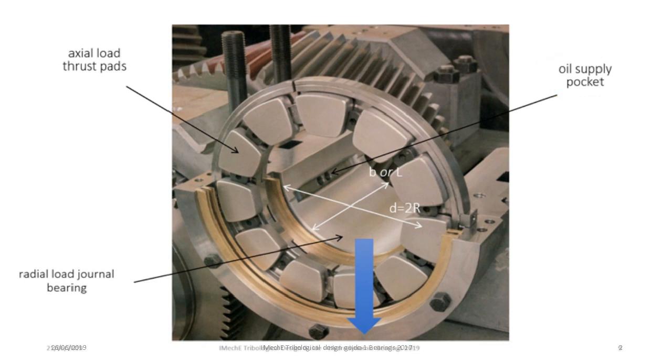Oil must be supplied at sufficient rate to compensate for its loss from the ends of the bearing. The ring of 11 more or less square pads are designed to carry the axial load. They are tilting pad thrust bearings. We won't talk about their design in this session, but they too depend essentially on the same mechanism, and are described by a suitable form of Reynolds' equation.